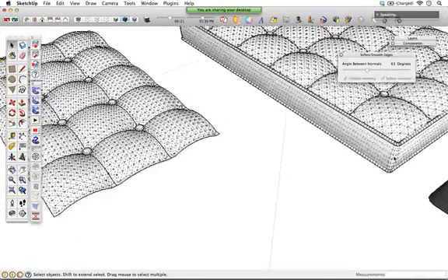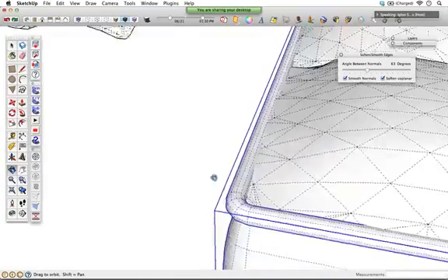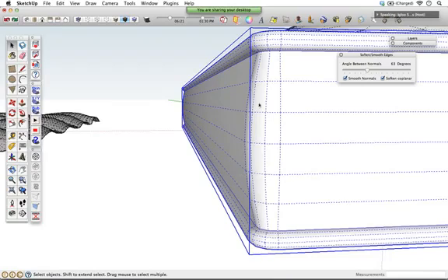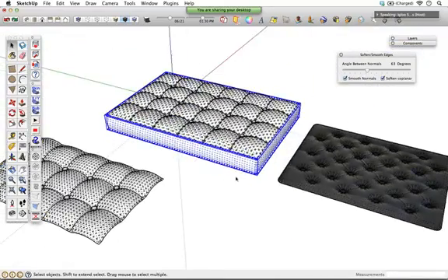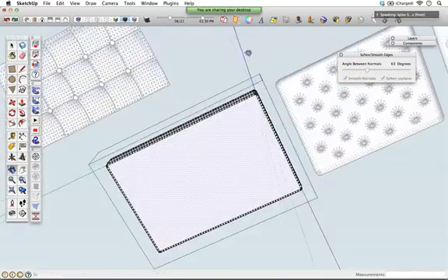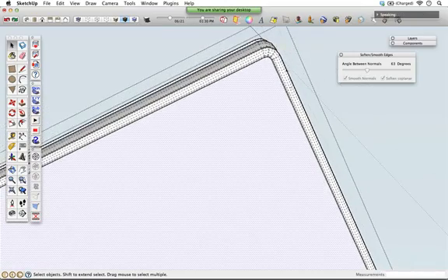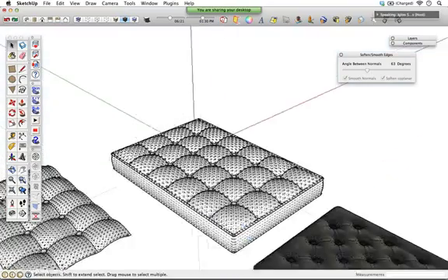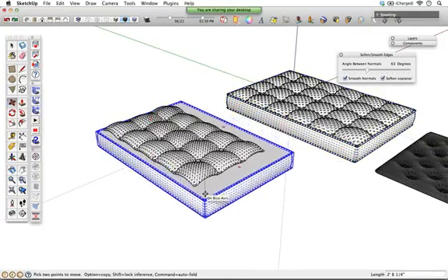And then all I did back over here was use the follow me tool. I drew a little profile that had that kind of beaded edge and a little bit of a billow for the side profile. So just drew this all as a little follow me tool extrusion and drew myself a rounded rectangle as a base to start with. So you can kind of see that the starting base had a little bit of an arc to it. So a little rounded rectangle starting base, and then sent this profile around that rounded rectangle to get the base for that thing. So I'll just make a copy of this and move it over, kind of a little cheat. I'll fast forward here.